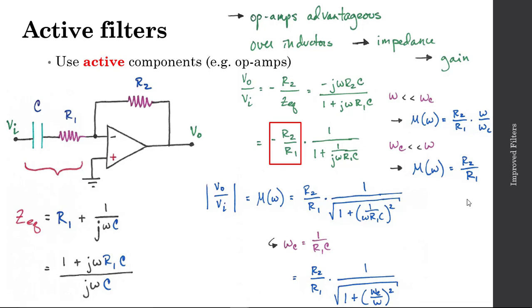What this tells me then is that this particular filter behaves as a high-pass filter. These lower frequency signals are getting attenuated, but my higher frequency signals are making it through and are subject to that gain. And it's also telling me that it's a first order filter, right? Because in my description of the magnitude ratio, this would be a 2k, k is equal to 2, therefore k would be equal to 1, and this would be a first order filter.